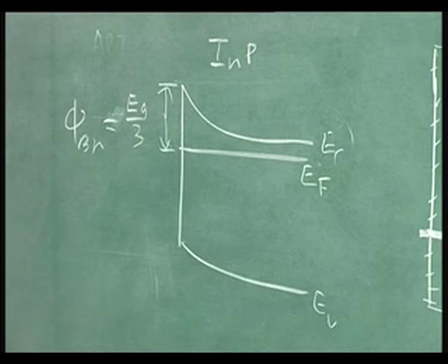In fact, you will not see in literature a MESFET made with indium phosphide. You do not see reports telling of an indium phosphide MESFET. You see reports and devices fabricated with gallium arsenide MESFETs. That is because you get high barrier height there. Here you do not get. It is not an ohmic contact, but it is a very poor junction.